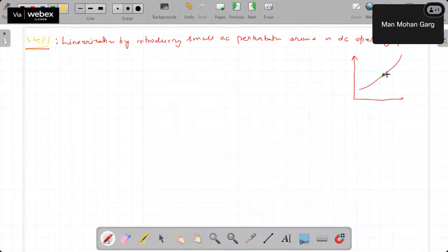But it may vary to 18 volt, it may vary to 22 volt. But you cannot say, I have designed for 20 volt nominal input, but the input voltage varies to 100 volt. That way we cannot design any practical system. Even our instruments have certain variation allowed in input. At home you have rated up to 230 volt, or maybe plus minus 10 or 20%, but if you suddenly feed 440 volt to that equipment, definitely it will not work.